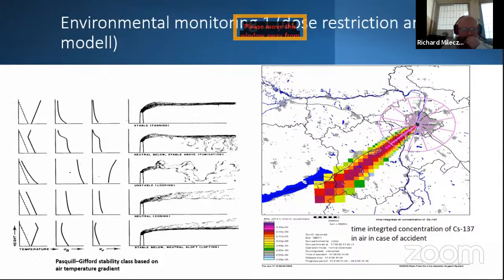One such model is the Pasquill-Gifford stability class. This describes how material will behave in the atmosphere once emitted from a chimney, depending on the temperature gradient of the air. It does not cover all possibilities, there are only 5 classes after all, but it is a sufficiently accurate approximation. The gathered data gets fed into these models, and the numerical results we get are fed into bigger models. For example, we get data regarding the temperature gradients in the area. Based on this, we figure out which stability class our area is in. Then, this gets fed into a model which tells us how radioactive material will propagate in the area.